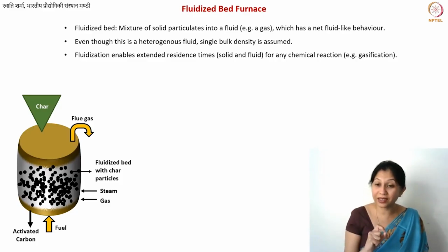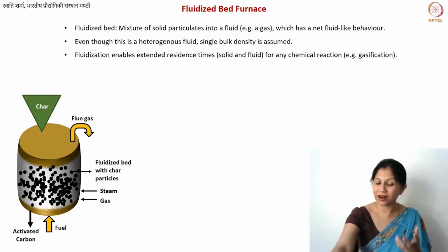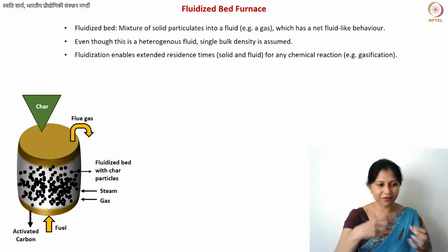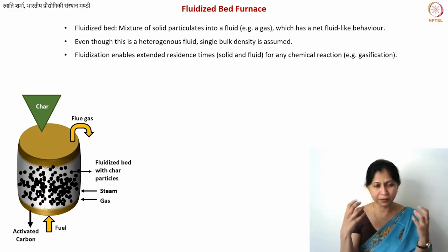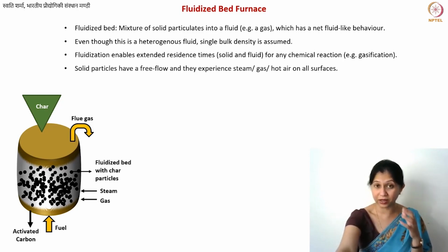Okay. So now here you can imagine that because the reaction is happening all the time, you actually need smaller residence times. In fact, if you end up having a very long residence time, you may end up losing your carbon. So the optimization of residence time becomes important, because the reaction is relatively quick, because all the surfaces are always reacting. It is a constant reaction. So it is important that you ensure you do not have very long residence times.